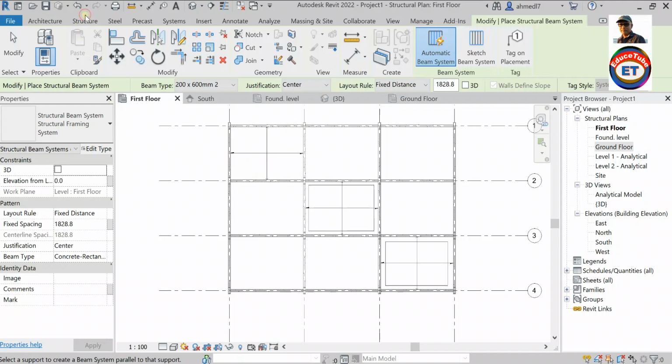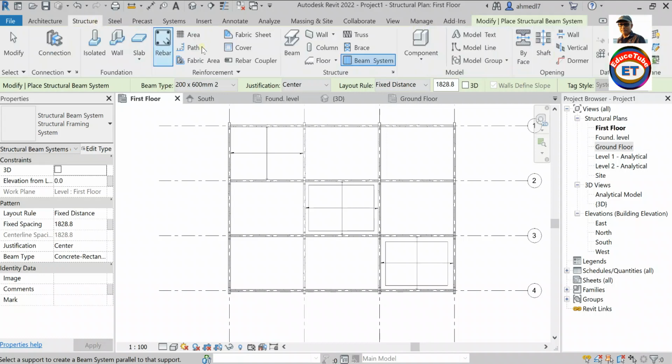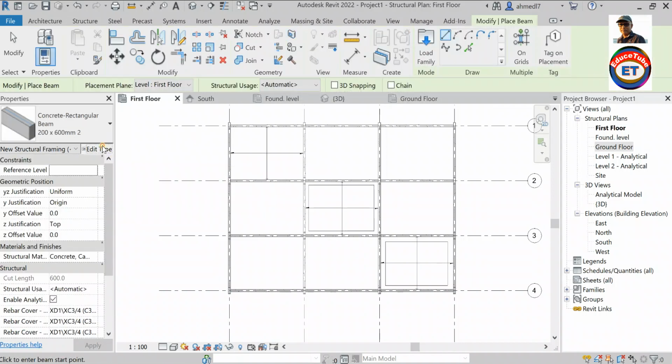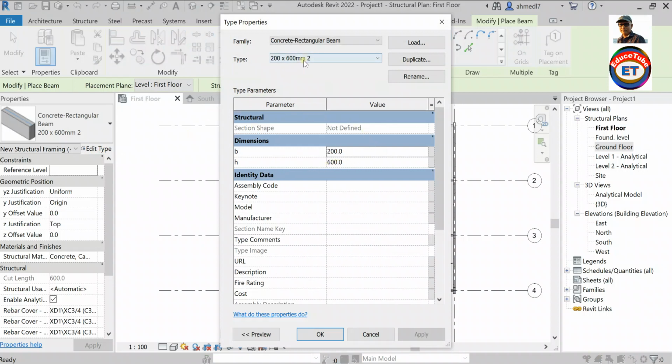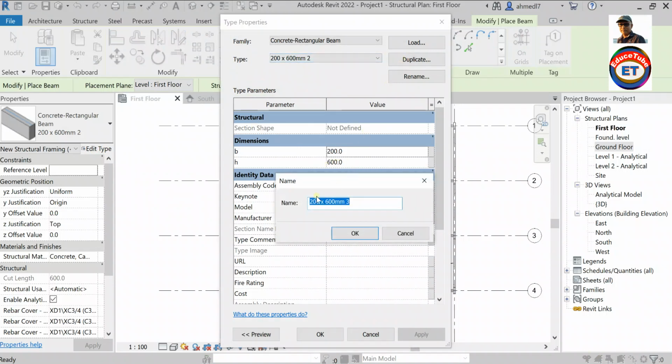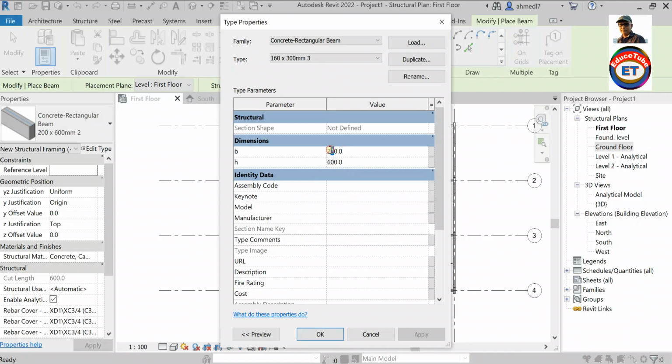So what I will do, say first I have to select the beams first, because I have to take a beam here of having, say, 160 by 300. This ribs beam I need, that is in between the blocks, 40 centimeter hardy blocks. So 160, and this will be say 30.